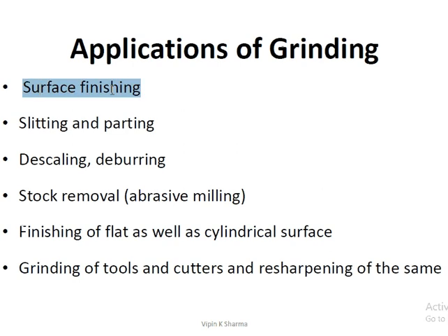Okay, so it is the definition of the grinding process. It is a material removal or material cutting process which engages an abrasive tool in the form of a wheel whose cutting elements are grains of abrasive material known as grit. These grits are characterized by sharp cutting points, high hot hardness, and chemical stability and wear resistance, as I have already discussed. These grits are held together with the help of some suitable bonding material.